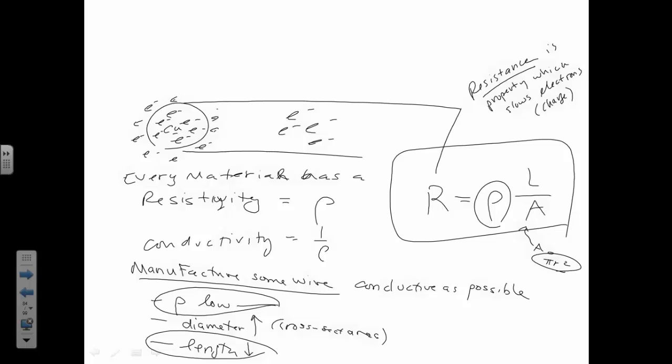So rather than having all these collisions and all this high resistance, I could buy an extension cord which, instead of a 14 gauge wire, which is a measure of how thick the wire is, I could go down to a 12 gauge or a 10 gauge or maybe even 8 gauge wire, because you can buy some industrial ones. You won't find them at Home Depot. You can get 12-gauge extension cords, but some are used for industrial purposes that maybe aren't quite this big. For certain big industrial purposes, you'll see extension cords like this, which can handle huge amounts of current.